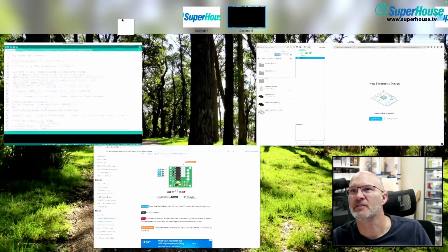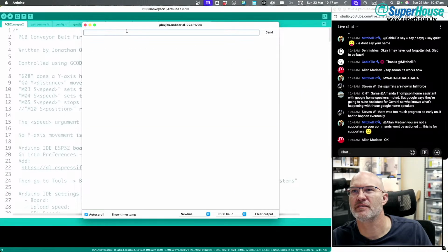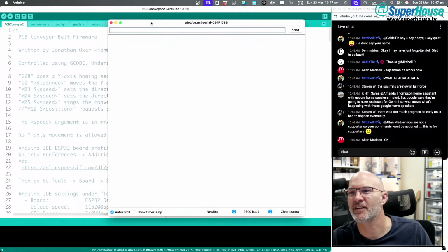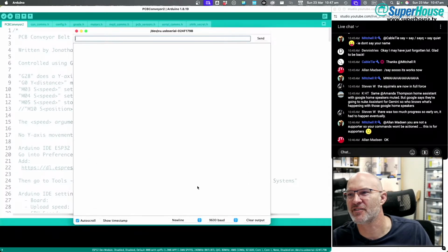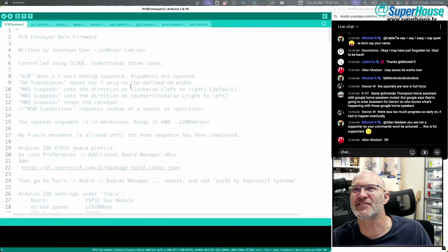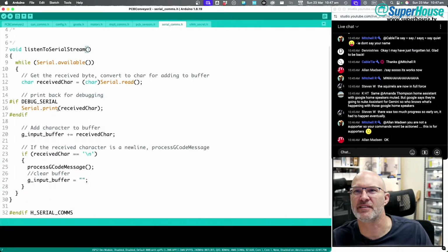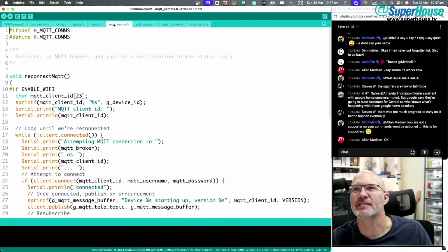And whoop. And let's just see. Can we do anything? Oh, it's at 9600 baud. Why is it set to that? Oh, that's right, because I was talking to a washing machine. All right, now I'll try. Apparently it doesn't like that. Did I do anything? Where is the serial comms? Is it that? Print back. It just sends it straight to the thing.